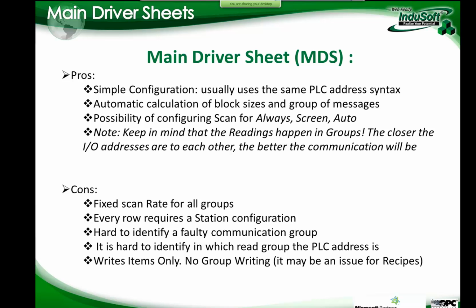If this is the first time that you're seeing anything related to communication drivers or InduSoft, we basically have two ways to configure how you're going to talk to the PLC. And the driver in InduSoft Web Studio, as I showed, is a separate module. So when you're configuring the tags database, you don't say if that tag is going to be an IO or not. When you go to the drivers module, as I'm going to show here,